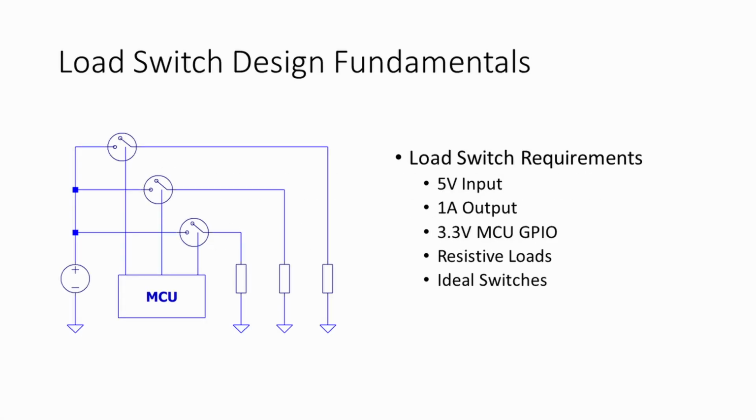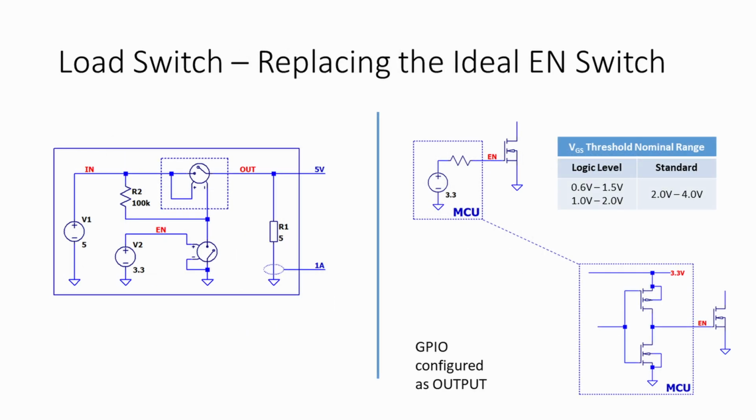In part two of load switch design, we'll replace the ideal enable switches with transistors and look into some of the key items driving part choice decisions. We can start with a MOSFET-based design for the enable switch. Since a 3.3 volt powered microcontroller is driving the gate of the FET, we need to select a logic level